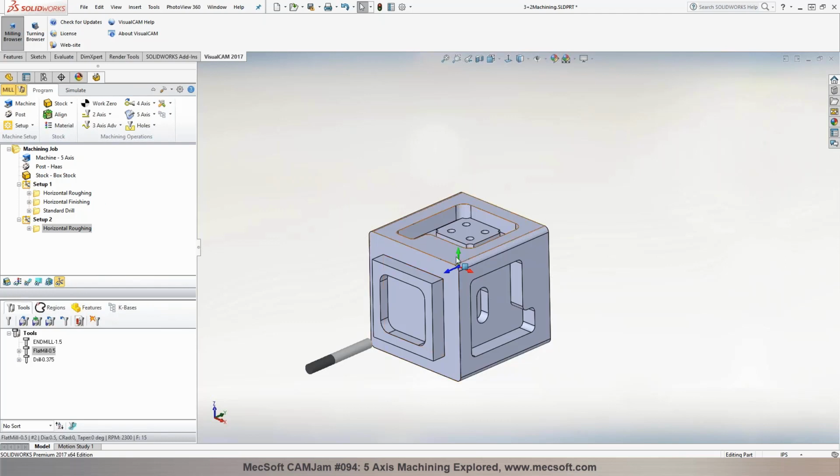Okay, so now, just to understand, if it's the configuration table head, basically I follow the same procedure, but probably the program at the end will post-process a G-code that handles the continuous movement between the axes. That is correct.